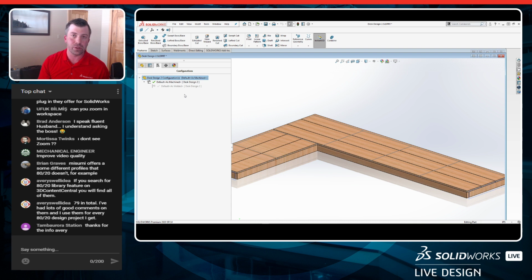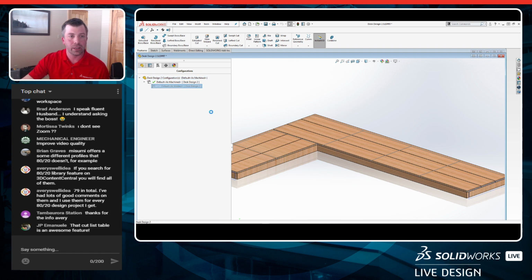Now you can use these as the as welded is going to be basically all your stock material. And then as we do the as machined, you can add in additional features to it. So I put a bunch of holes all along the back board for cabling of this. That would change the properties of that board and pull it from the cut list. Don't need that.